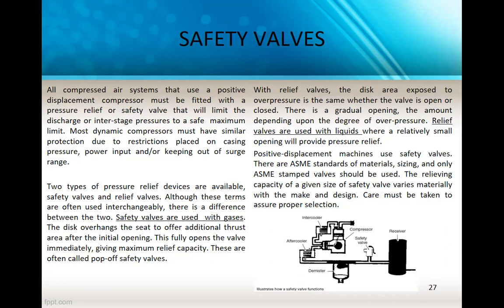These are called pop-up safety valves. With the relief valve, the disc area exposed to overpressure is the same whether the valve is open or closed. There is a gradual opening, the amount depending upon the degree of overpressure. The relief valves are used with liquids, where a relatively small opening will provide pressure relief.